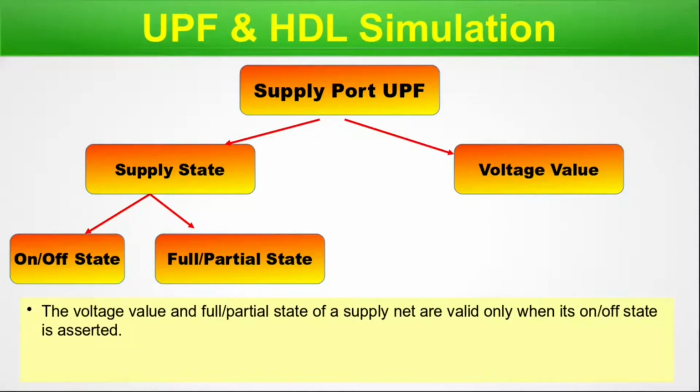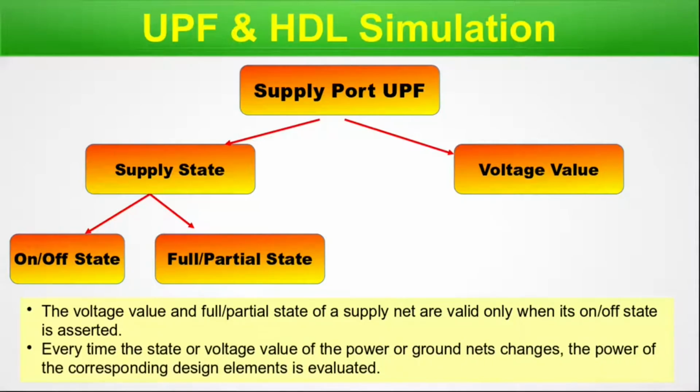The voltage value and full or partial state of a supply net are valid only when its on or off state is asserted. Every time the state or the voltage value of the power or ground nets changes, the power of the corresponding design element is evaluated.